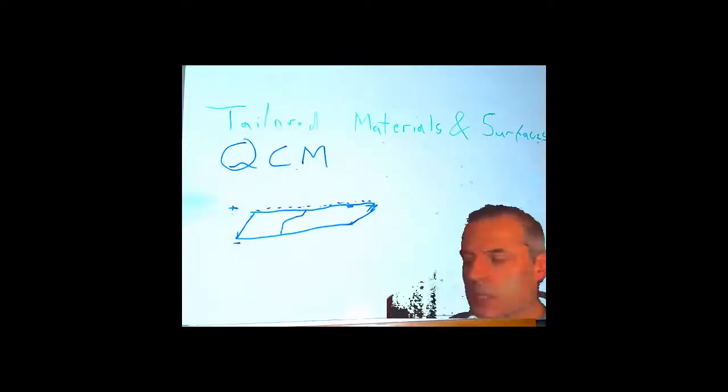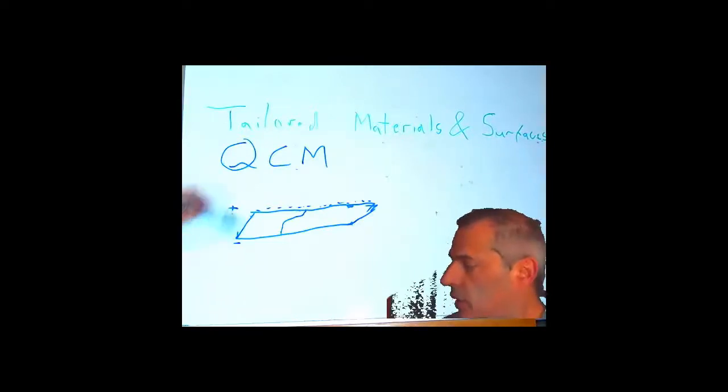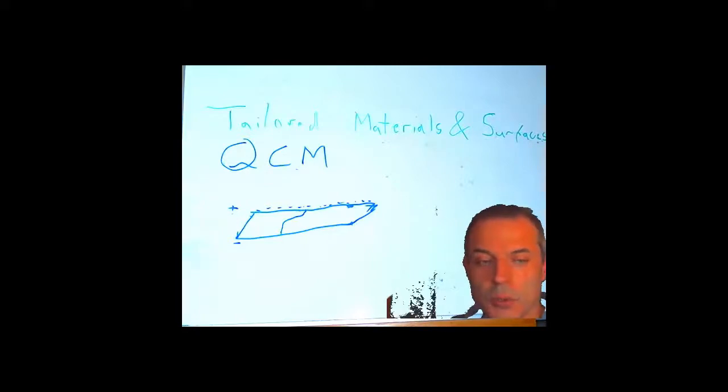So if we can measure the resonance frequency of our quartz, we can measure something to do with the added material. If it behaves itself very well, we can measure the mass of the added material and guesstimate the thickness, and we can get down to sub-monolayers.